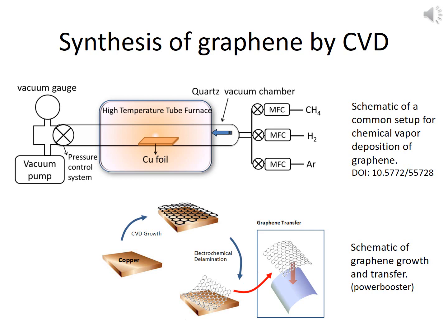The copper etching and graphene transfer process always leaves copper remains on the bottom side of graphene previously attached to the copper foils. In addition, at a typical graphene growth temperature of 900 to 1000 degrees C, copper gets partially melted and sublimated. The generated copper vapor easily contaminates the CVD chamber as well as the grown graphene from the top. CVD process can be of various types: thermal, plasma enhanced, cold wall, hot wall, reactive, and so on. This depends on the characteristics such as the material quality, precursor, the width, and the structure required.